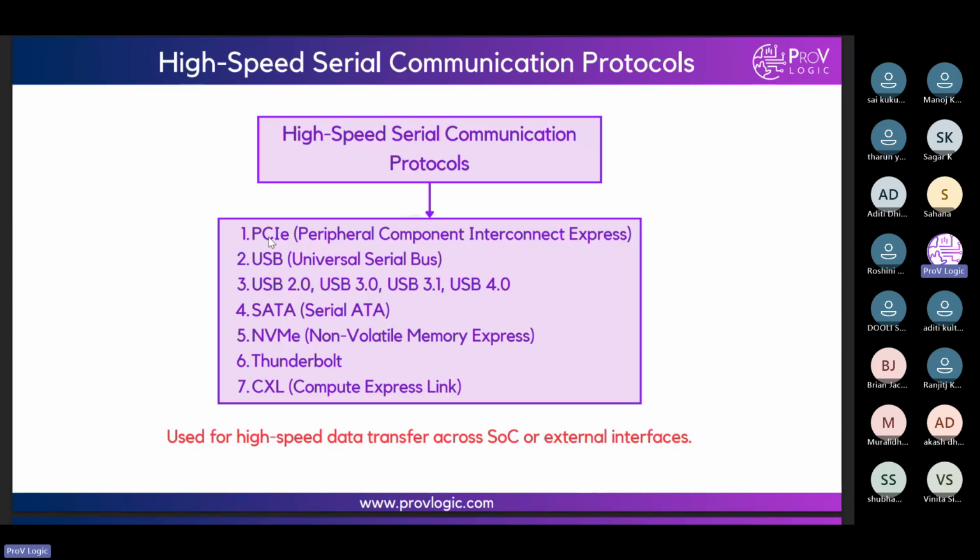It's not parallel, it's high speed serial communication, and we connect in terms of lanes. Lanes in the sense multiple lanes we will connect at a time. Multiple data transfers can be done by using the lanes. Suppose the configurations we have are x4, x8, x16. It's not parallel communication, serial only, but 16-bit data we will communicate through the lanes.